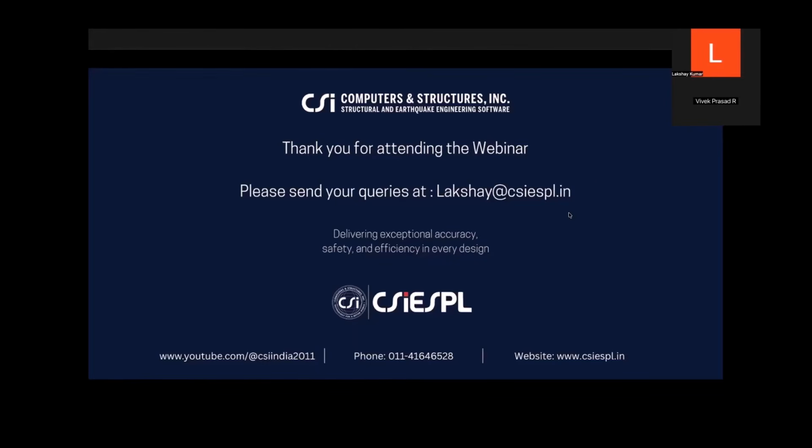How is it possible to identify tension in vertical members using the response spectrum analysis? You will have to see the design force output I just showed you in the presentation. If one of them shows a positive value, then it is in tension. Otherwise, since this is a combination and not viewed in isolation, you will have to see the design combination output for such effects, whether it is really going into tension or not.